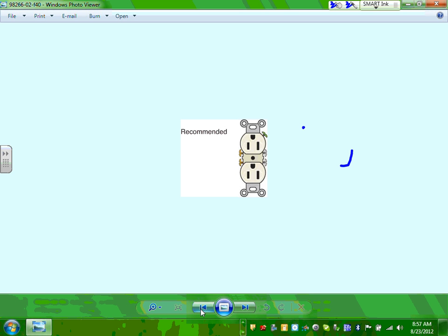I don't know. So what do? Yes, sir. A lot of plugs come out of the wall where they lean down. So wouldn't you want the grounded conductor to be the last thing to come out of the wall as it falls out? That's by design, though. They design them a little bit longer. If it was to fall out this way, it'd be the first thing to come out of the wall. So wouldn't you want it to be the last thing to come out? I hear you. It cuts the ground first instead of the hot.